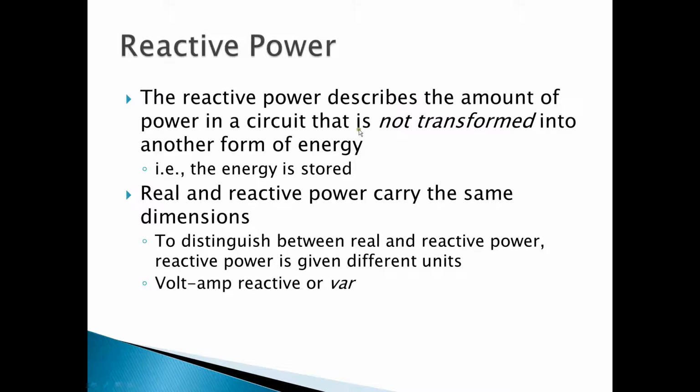Reactive power, on the other hand, describes the amount of power in a circuit or the rate at which energy is not transformed or is stored within elements of the circuit. Both real and reactive power carry the same dimensions. They're both the product of current and voltage. And so they can be conceived as being watts.